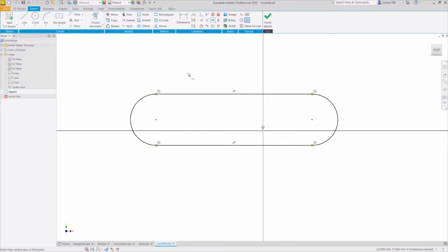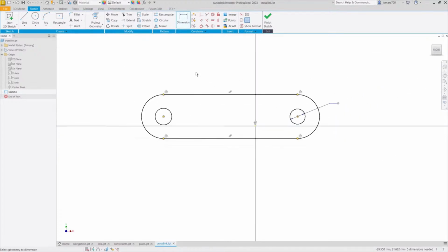Selecting cancel. Let's add the circles, hitting Ctrl Shift C, dropping them on these center points, left click, and the diameter for this hole to be 10. So with that, I'm going to hit D for dimension, selecting this circle, placing our dimension here, key in 10, hitting enter.